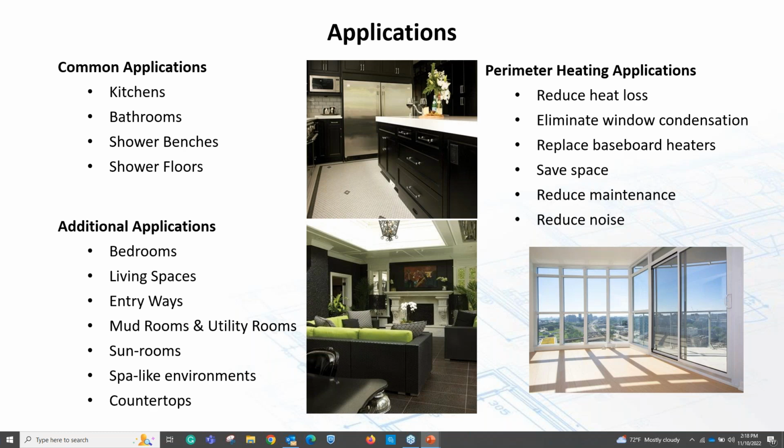Yeah, also, in more commercial spaces with large windows, you tend to have a lot of condensation in the wintertime when you run a standard HVAC system. These will allow you to run that electric radiant heat floor, and you will not have that condensation. You'll keep that area heated up, nice and warm, and basically, as long as you have modern installation practices, you'll have a much more readily heated space. I'm going to say it'll feel better, as we say.